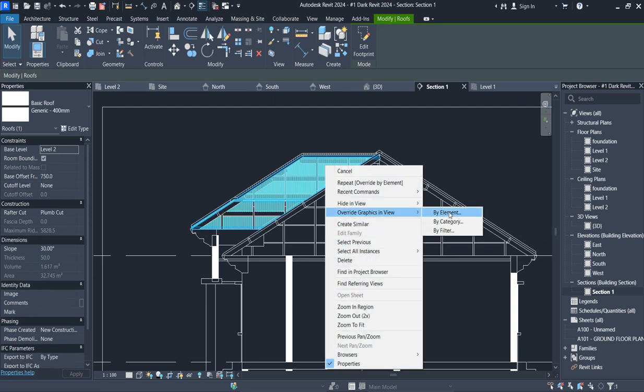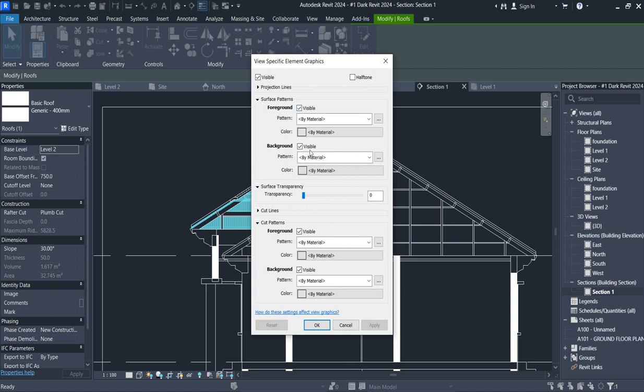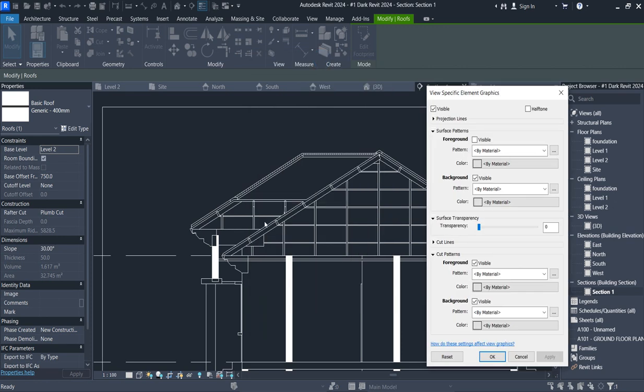So graphics override is what you do by elements. So I say background, click. Can you see it's not what you're supposed to? So when you click this one and see it should apply, this one will go. But you can imagine it has already affected this one. So you have to select this one and create another inverse behavior towards this one.